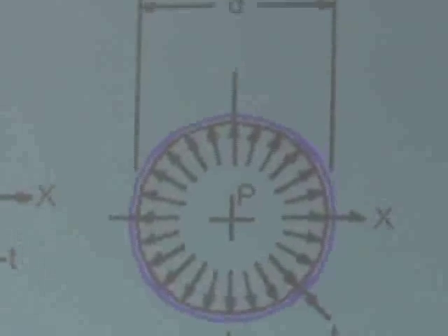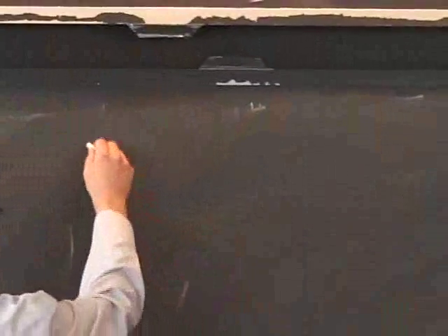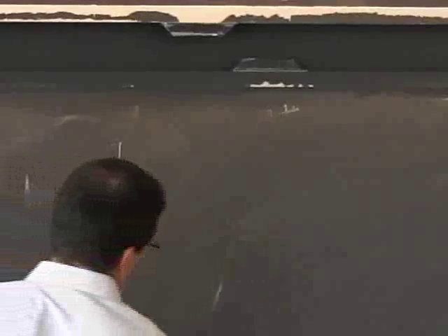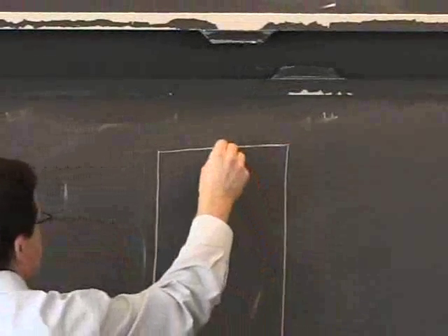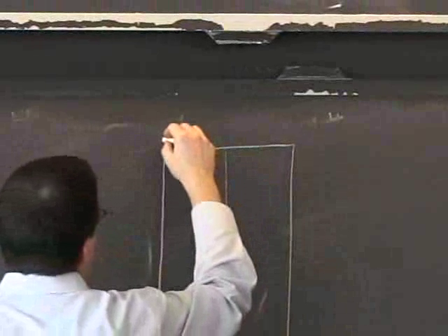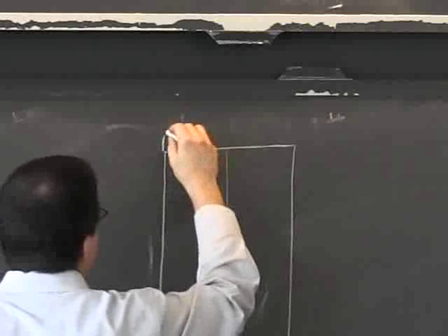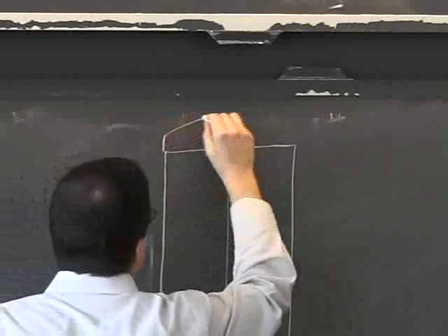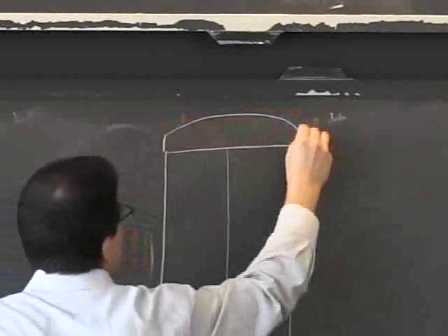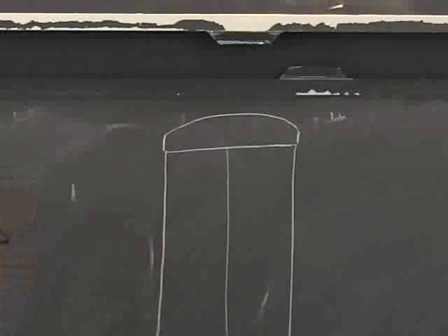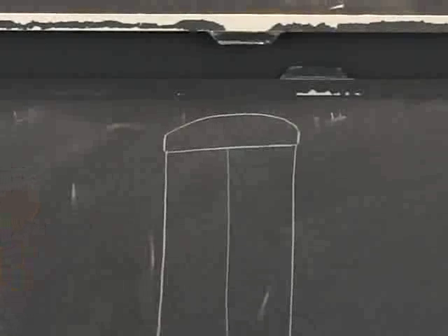The way you would want to build it is, say you have your flat sheet for the central portion, and typically it's going to have a seam weld going all around it. And then you manufacture ends that will look like this. Could be just stamping, not necessarily deep drawing.